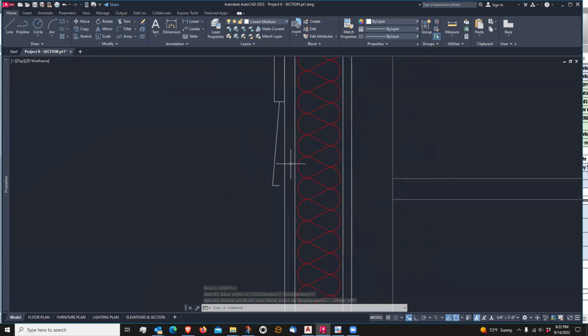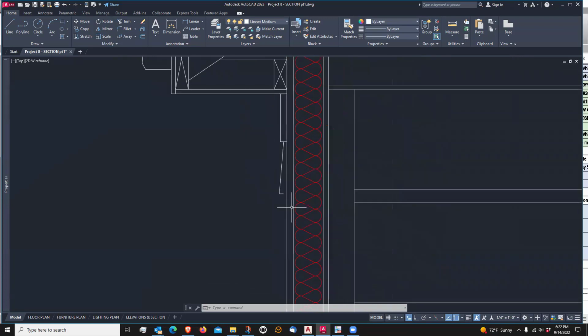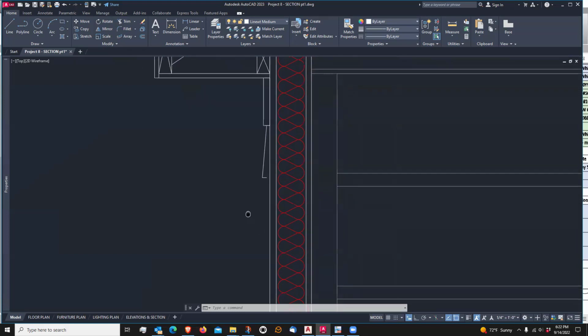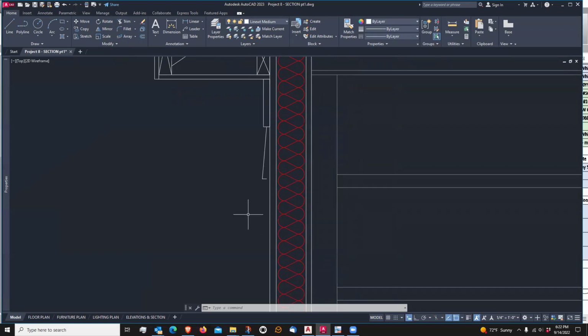So it's kind of a little bit away from our sheathing here. This is our plywood sheathing on our wall, if you remember, and then the shingles graphically, we're showing it pulled away a little bit. In actuality, there would be building paper that goes down here, and then the shingles would be nailed literally right through the building paper onto the sheathing right here. So they would actually touch the sheathing, but I'm not showing that just to make it graphically more readable, more legible.